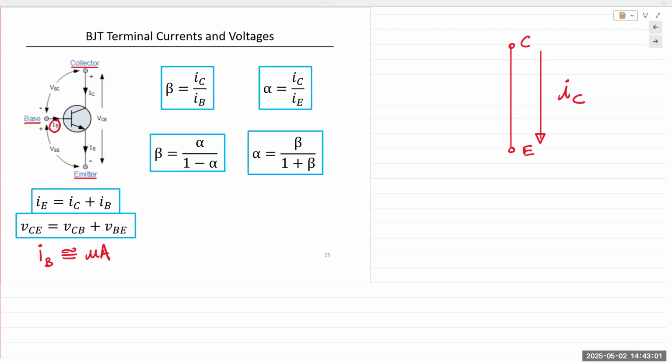The point of a unity gain amplifier, which is actually very important in electronic circuits, is to isolate a specific input from the output. Typically in electronic circuits we have cascading connections. We'd have an input, then some sort of circuit. The input is fed into that circuit, the circuit has an output, that output goes into circuit number 2, circuit number 2 has an output that goes into circuit number 3, and so on and so forth.